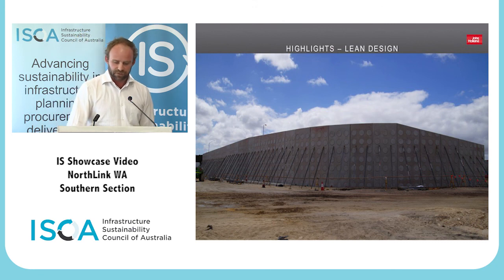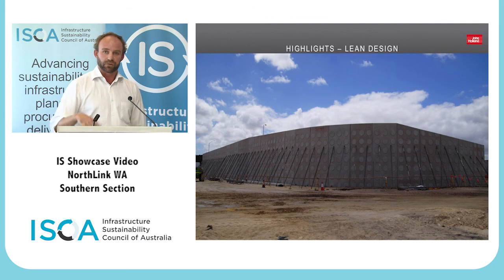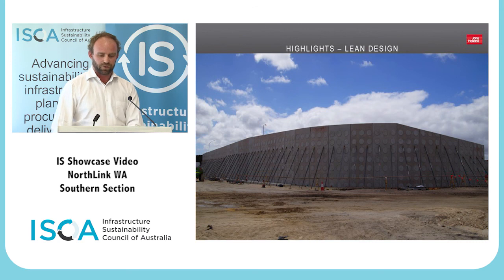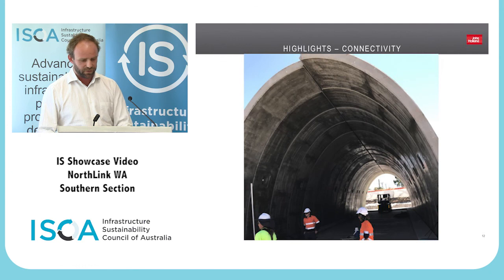And in some cases, passive design options, such as around drainage, where you avoid pit and pipe and you avoid introducing hard assets, but you go for vegetated drainage, swales or basins, the performance was able to be improved whilst the impacts were reduced. So that lean design was an ongoing focus, which yielded significant benefits in the scheme of things. The next benefit is about connectivity.